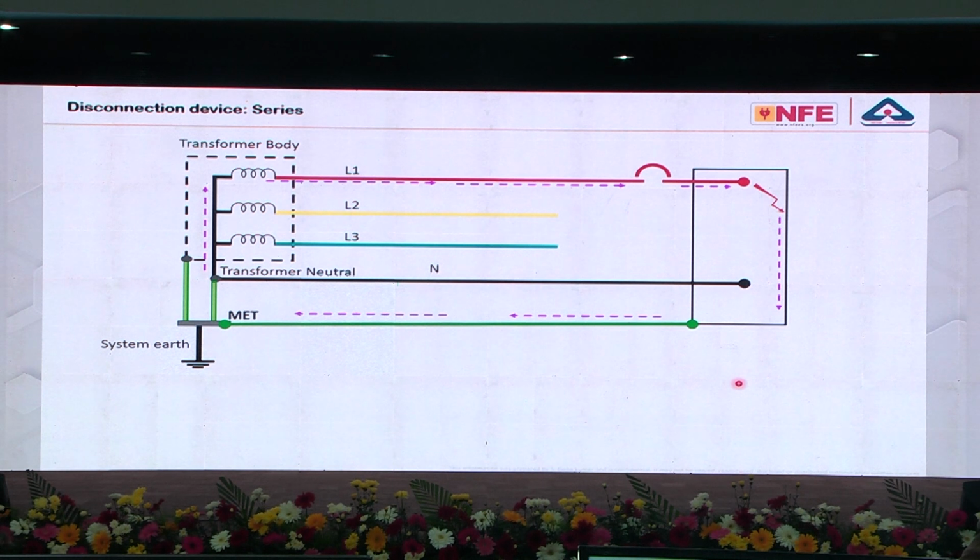One point you should always keep in mind is, generally electrical engineers say that fault current goes to earth. Please note that earth is not a current absorber. Earth cannot absorb current so much. No, fault current has to go back to its source. Current leaves the source and returns back to the source.